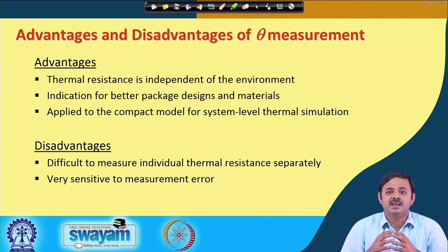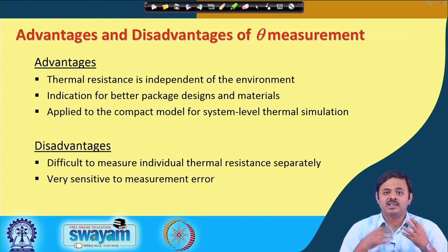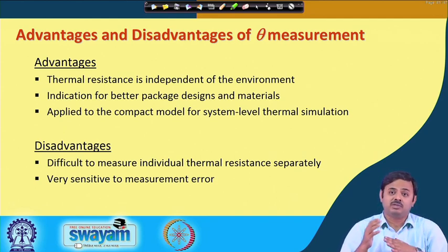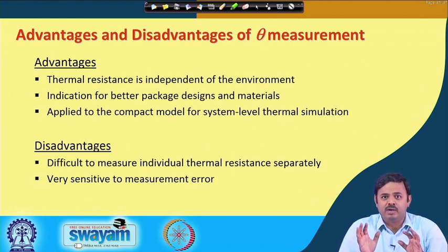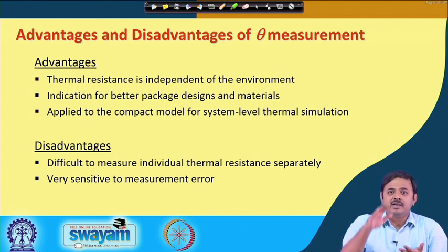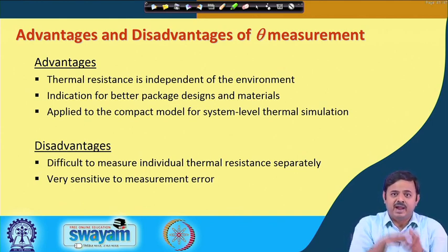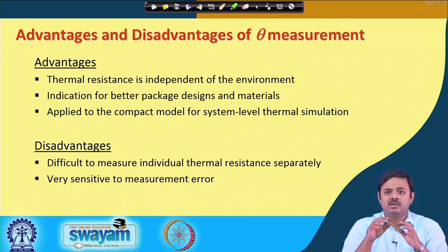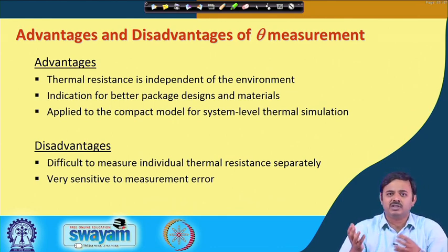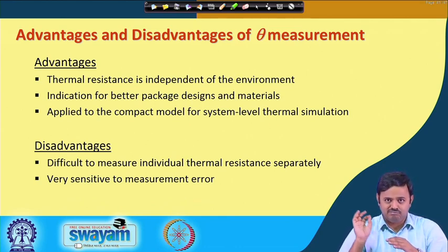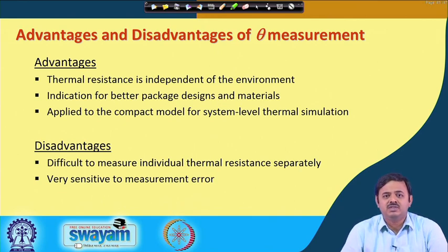And when I say practicing engineers, of course the thermal engineers do come up with these values. So, they have to think a lot more. They have to worry about conduction, convection, radiation, how can I increase the heat transfer coefficient, all that stuff, that is their job. But their final aim is to reduce theta as much as possible, and then give this value to the non-thermal engineers, who are then going to use this value for their package level models, system level models, to determine the maximum power that they can put into this piece of silicon, and so on and so forth. From that point of view, this is very, very useful.